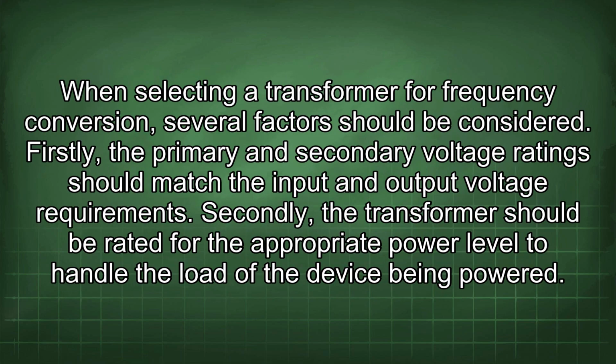When selecting a transformer for frequency conversion, several factors should be considered. Firstly, the primary and secondary voltage rating should match the input and output voltage requirements. Secondly, the transformer should be rated for the appropriate power level to handle the load of the device being powered.